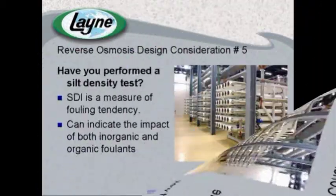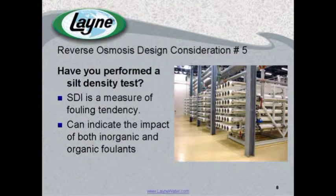Last consideration I want to leave you with today is, have you performed a silt density test? The initials SDI stand for Silt Density Index. And if you haven't done that, I would encourage you to make sure that you do that prior to heading down the path of designing or purchasing a reverse osmosis system.